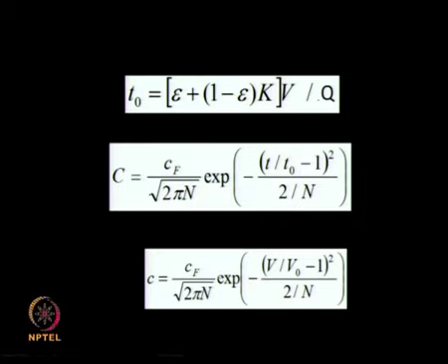In fact vendors, when they sell a chromatographic column, mention how many theoretical plates this particular column has. The larger the number of theoretical plates, the more efficient the column is in separating; the smaller the number, the less efficient the column is relatively. So when we buy a chromatographic column, we always look for the number of theoretical plates and then make a decision on how good the separation efficiency of the column is, and so on actually.